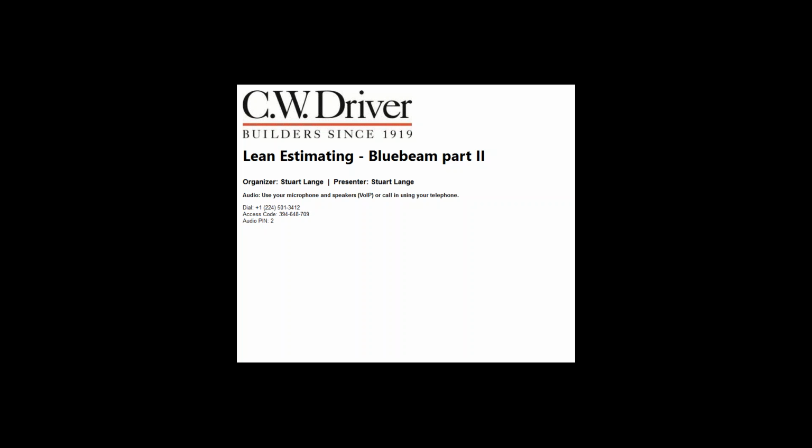Now you got something there that I don't have. I missed a step. Click somewhere. Add Open Files, okay, and then click Next. All right. So now we want to go by page label over here on the left, and then we'll double check our settings. So click on Settings up here on the right side. We just did the sheet title, so we don't need this filter. I could turn it off, no filter, or it doesn't really matter. I could leave it on.